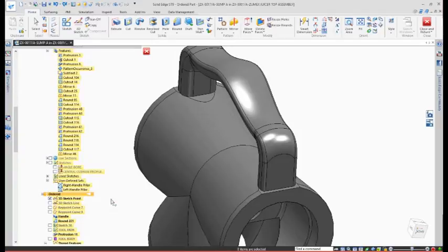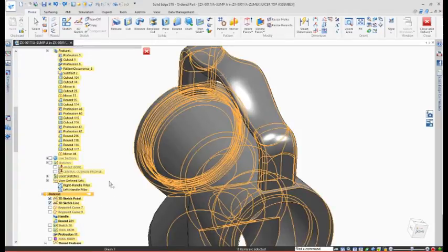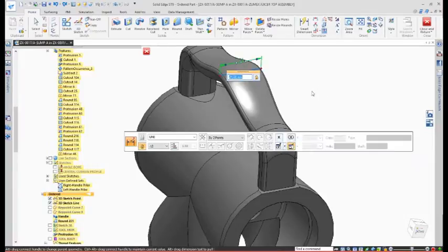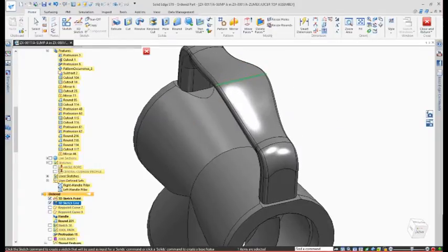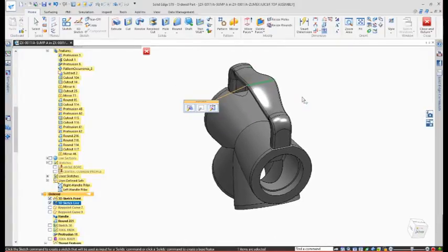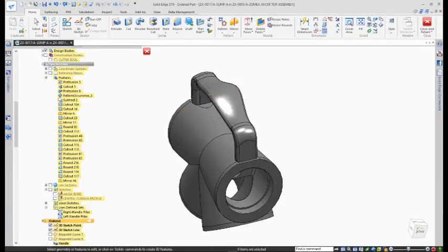Well, there's a little bit more changes to be made. The rotation looks like it did the job, but you know, the handle could probably be a little bit beefier. Let's use another ordered sketch, maybe through dynamic edit, and take this synchronous hybrid model and still do yet another ordered modification. Pretty snazzy. Hybrid modeling inside Solid Edge. The best of both worlds.